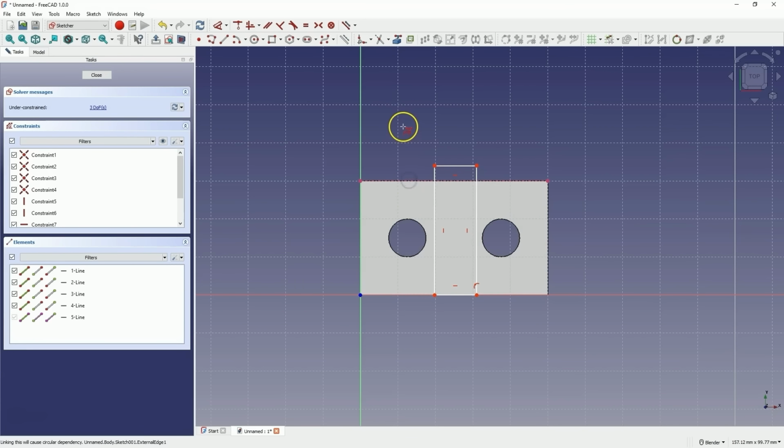Let's select this line. Now right click to cancel this command, and here, as you can see, a line has been created, and now we can use this line to link the sketch with the solid, and I would like to place this corner of the rectangle on this line. That's why I select this point, select this line, and select the coincident constraint. And now the rectangle is linked with this solid in such a way that this edge of the rectangle is linked with this edge of the solid, and this edge of the rectangle is linked with this edge of the solid. The rectangle does not yet have this dimension defined and does not have a specific location, but this dimension is already defined and we cannot change it.